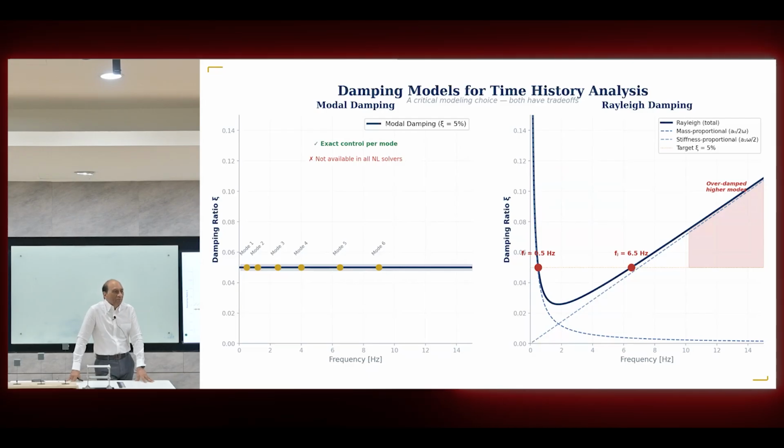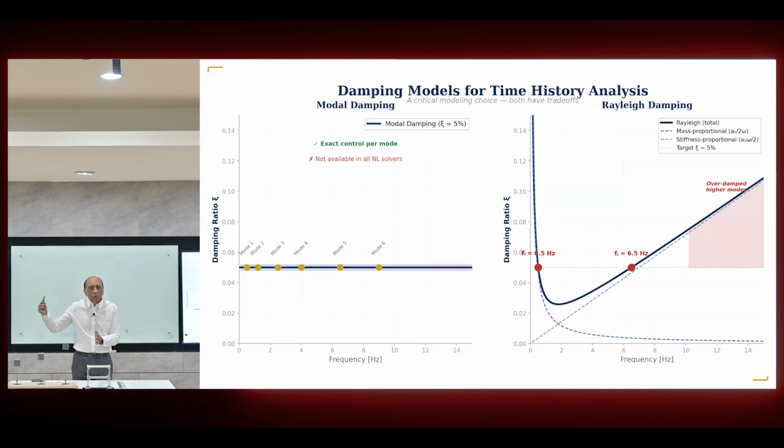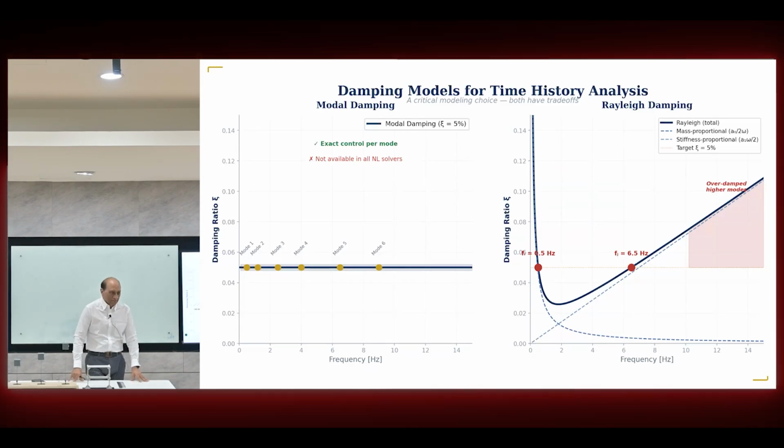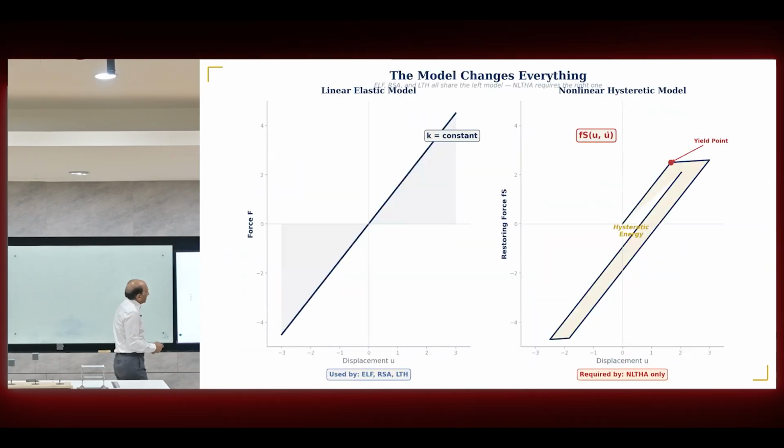We don't need any combination rules, because when we are running the time history analysis, we don't need the natural period as an input. It's just the mass and stiffness. And that's why it captures the actual response. Yeah, so this is the other important thing.